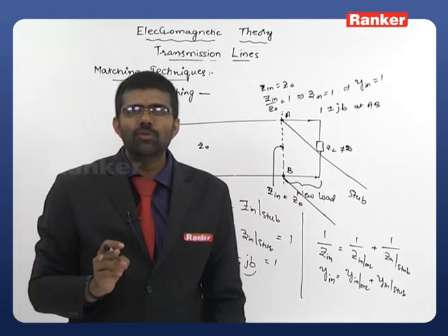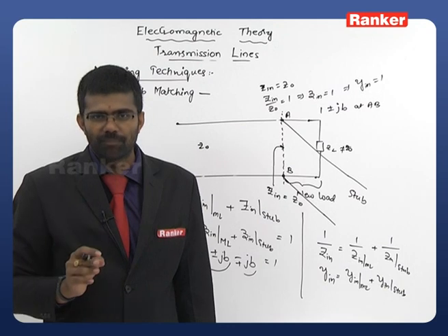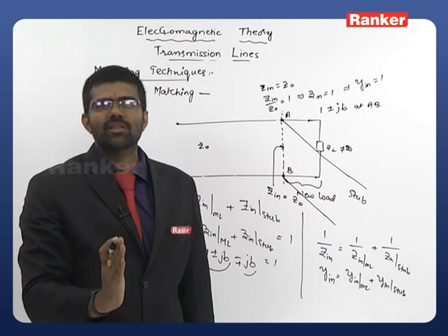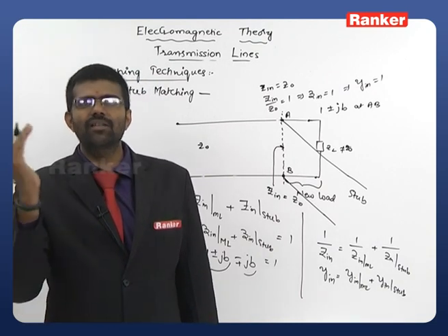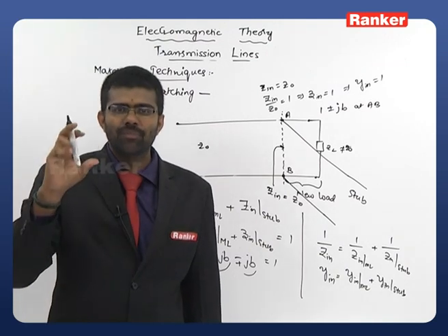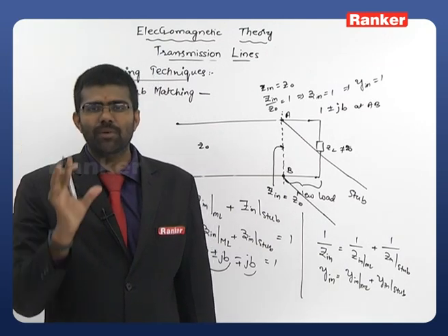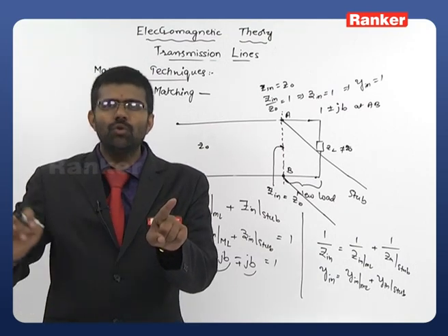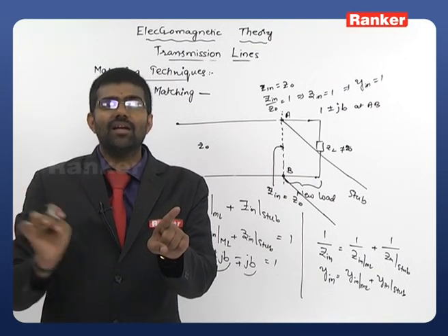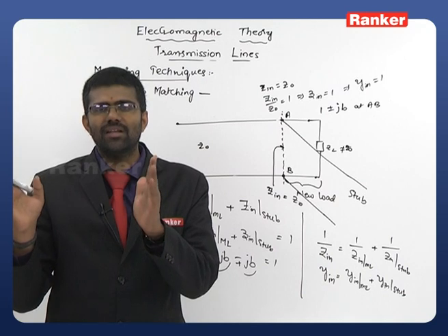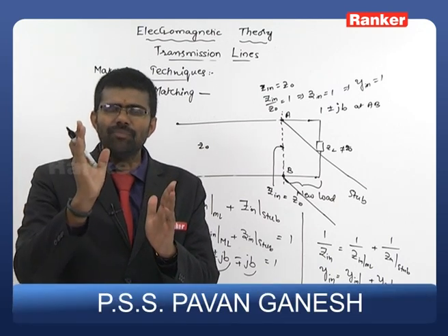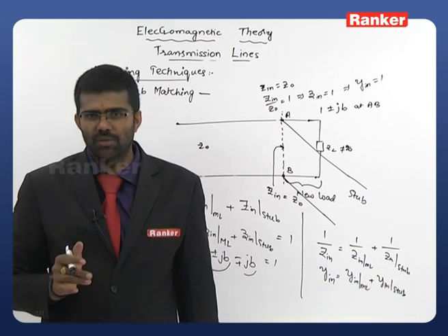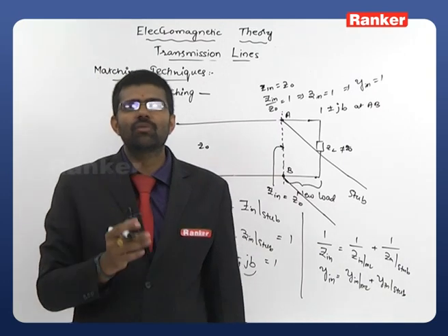Now you have to solve this problem using our Smith chart, and that will be very easy to solve. You are at the load. You are moving towards the generator. Somewhere you will get 1 plus or minus jB admittance. Now eliminate that plus or minus jB. For that, connect a stub. The required input admittance of the stub is minus or plus jB, that is already known to us. So from that point to the short circuit point, go to that one and calculate the length of the stub. Like this you can calculate the parameters like the location of the stub, required input admittance of the stub, and the length of the stub if it is short circuited or open circuited. So with the help of this, easily you can go for the matching application.